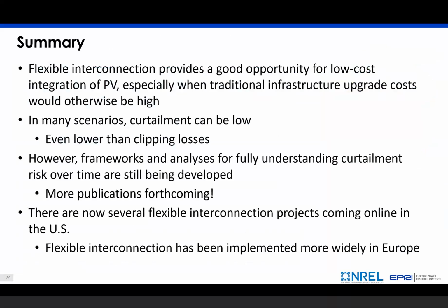So in summary, we want to just point out that flexible interconnection can provide a good opportunity for low-cost integration of PV, especially when traditional infrastructure upgrades would otherwise be high. In a lot of the scenarios and implementations we've seen, curtailment can be low, often even lower than what clipping losses would otherwise have been, to hopefully help mitigate developer concerns about potential curtailment.